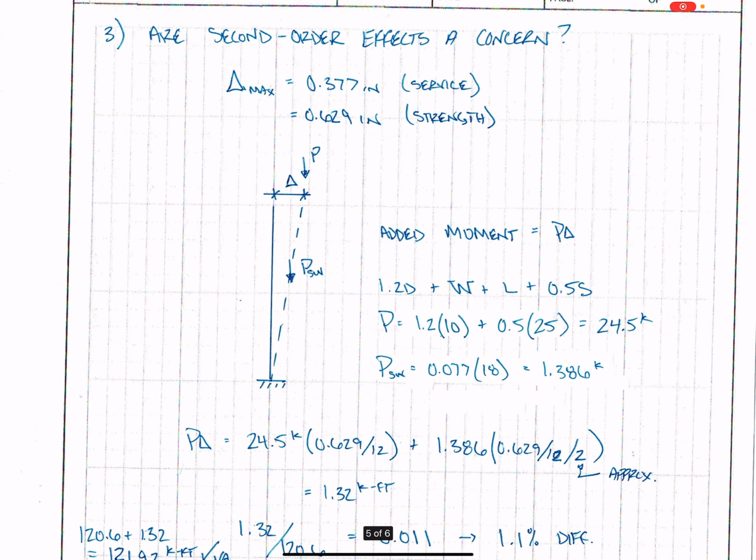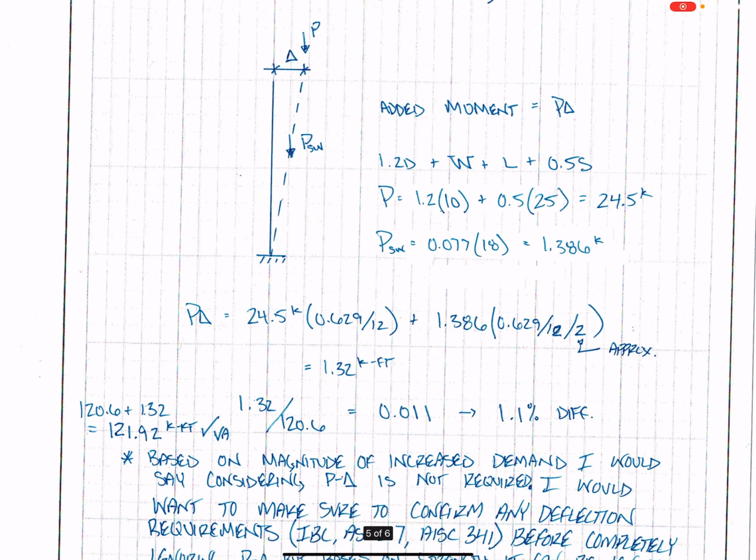Second order effects were the concern. Some of you did this differently, as opposed to including the self-weight value, but overall VA does it, and it did it non-iteratively because when it is pushing that member over, the stiffness it gave the member was a function of the deflected shape of that member. So as it moved over, it changed the stiffness, and so it was essentially doing the iteration in one step. Right? And so I think everyone got very, very close.